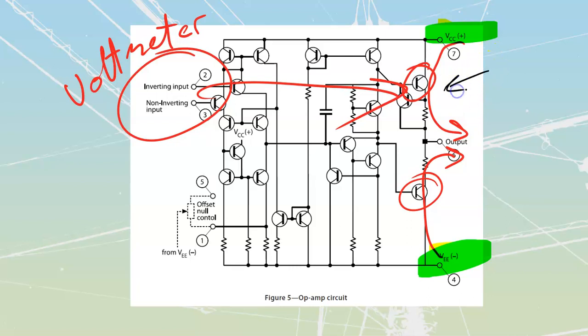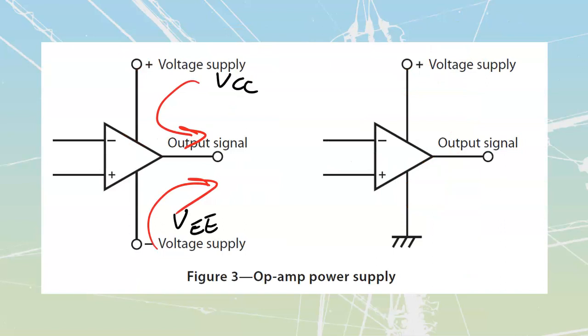What's the voltage drop across the transistor once I get that transistor all the way over to saturation? Well, we're going to drop about 0.1, 0.2 of a volt, maybe a little bit more, maybe a little bit less, but we are going to have obviously some sort of a voltage drop, as well as another voltage drop right over here on this value of resistance. So there is going to be a little less voltage than what's coming in that is going to come back out of these over here. Remember how we said before that an op-amp is a dreamer.